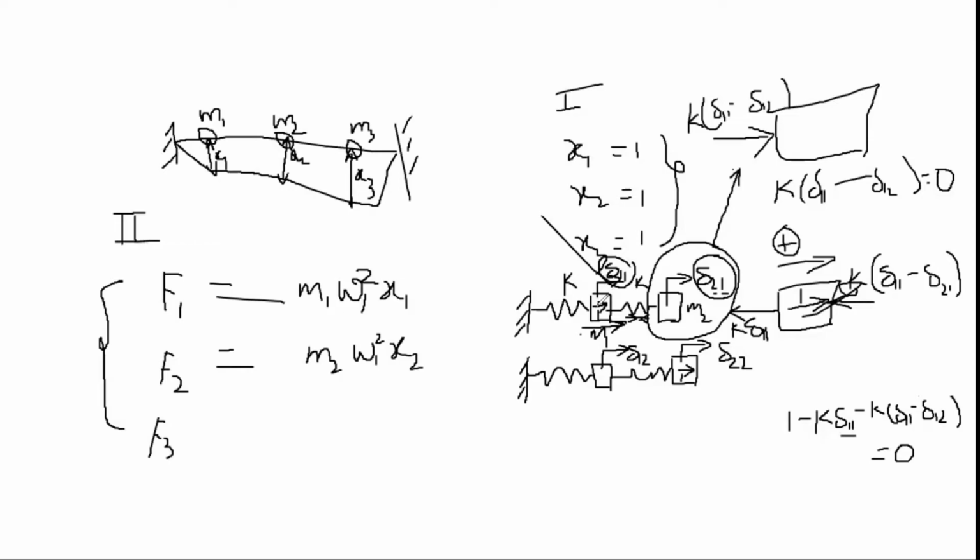Okay, so this is how you would calculate the value of all deflections because of the inertial forces. Mind here, remember that these deflections are because of unit load. So when I apply an inertial load, then the total deflection at these points would be force multiplied by this deflection. Okay, because this is the deflection because of the unit load, so the total deflection when the inertial forces are applied, this would be multiplied by the force applied there.